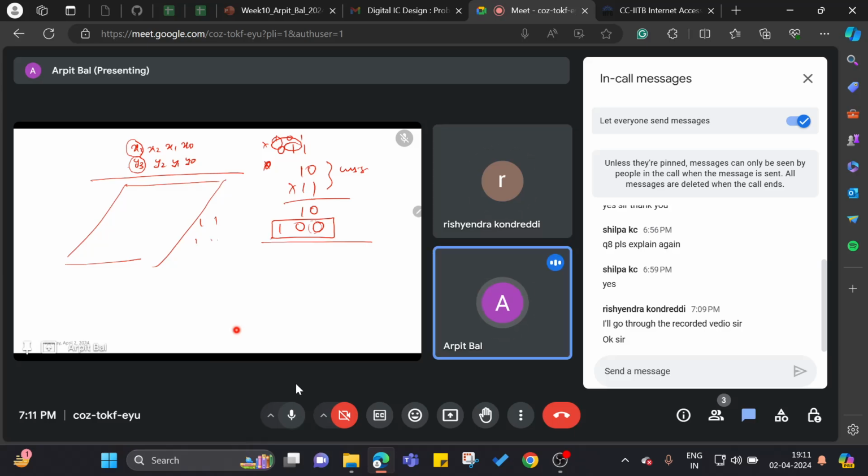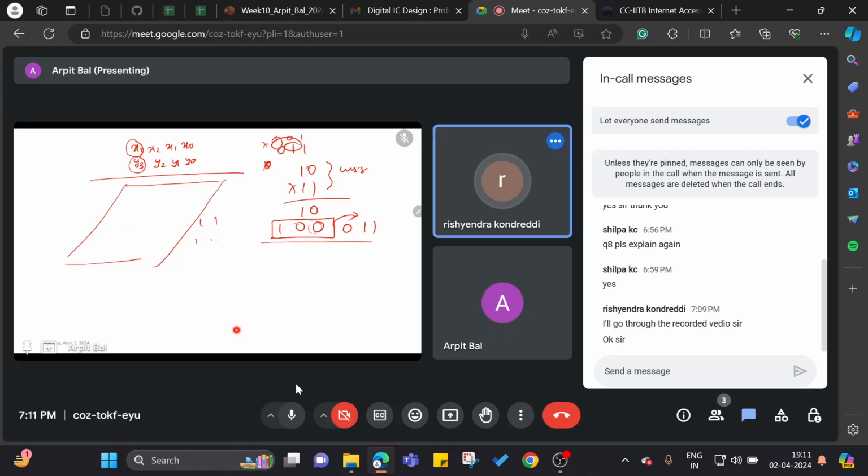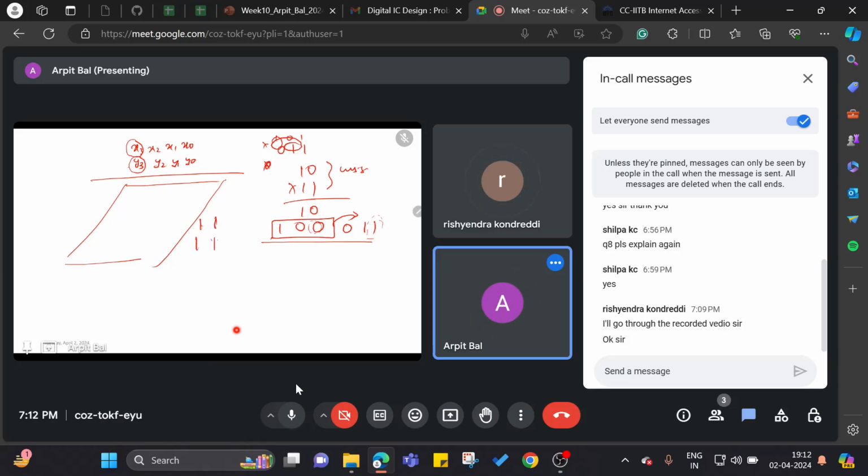If this partial product has a 0 present and you want to take the inversion of that, then it will be 1, 1. So it appears like a 1 appears out of nowhere, but it is actually inverting that partial product. Understood now? So that's how those ones appeared there. This was supposed to be vacant, but because it is multiplied with y3, we have to do the inversion, and those vacant spaces were occupied by 0 earlier. Now when inverted, it becomes 1, 1.